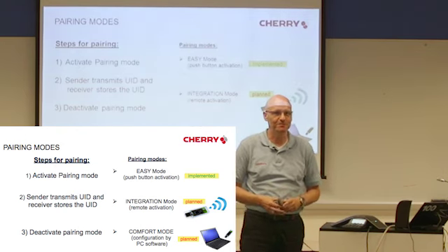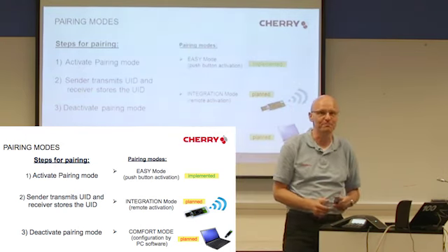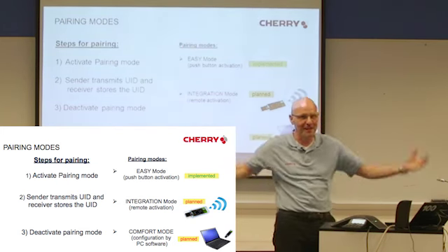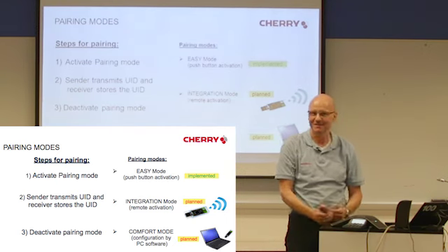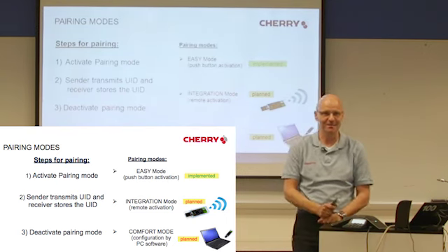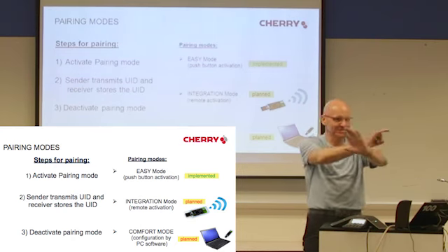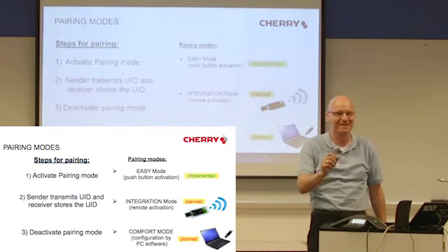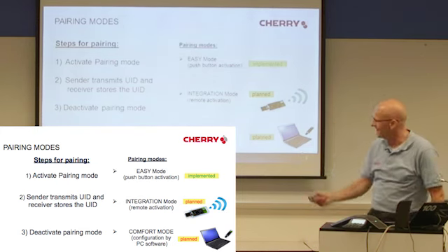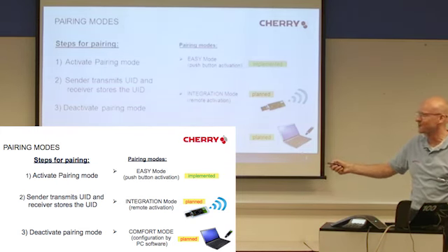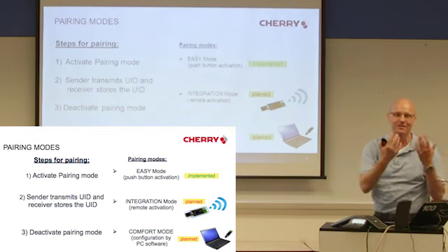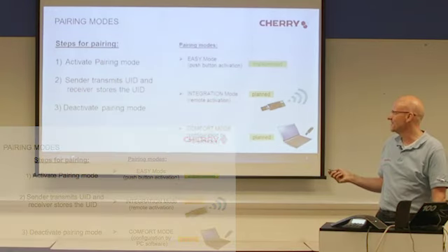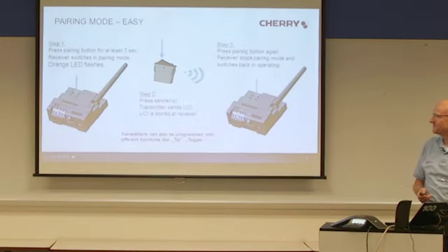So it's not possible: when he puts the receiver in pairing mode and on the other machines senders are operated, he would collect all these senders to his receiver. He cannot. He would have to stop all machines, a complete manufacturing stop, just to learn 1 sender to his receiver. It's impossible. And this is the reason why we plan a so-called comfort mode. So he could do it on a PC and all the other machines can keep working. So that's the reason for a comfort mode.